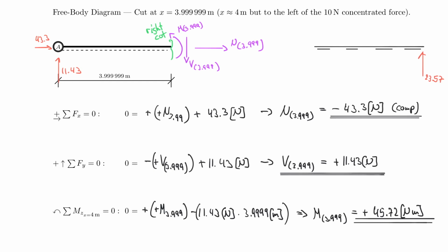I also had two other forces acting. One was directly at the cut here, which was 10. And then I had a sloped force here with 50 under an angle, so 50 and 10. And if you were to make this cut here now, you would find that you have the same answers for your shear force and your normal force and your bending moment.